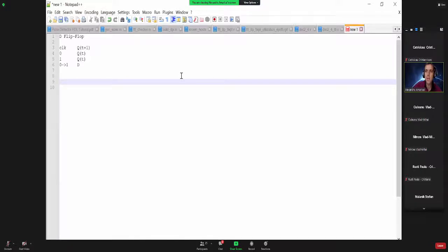The moment they load the value is the same, because they are connected to the same clock input. They load the new data, they make their update, when it is the positive edge of the clock signal. So actually it's at the same time, because that positive edge occurs for all the registers within the design at the same time, okay.